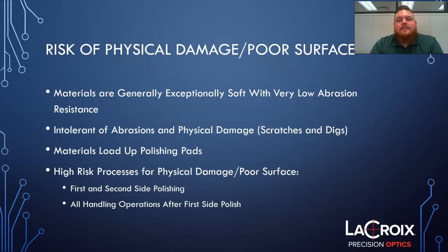And most definitely during the manufacturing process, these optics often have to be physically handled in order to remove them from the polisher, load them in the polisher, move them into cleaning trays, the hand cleaning process, the inspection process. During all these processes, they are very susceptible to scratching if the operator has a small piece of dirt on their hand, or a small shard of glass that came off the edge of the part. They're also very susceptible if you place a convex surface down in a tray in order to transport the parts from one manufacturing cell to another, they can very easily be scratched by the bottom of the tray.